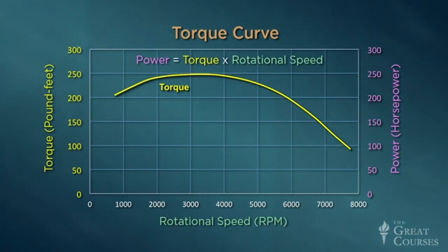On the high end, this deviation from the ideal is the inevitable result of mechanical friction, as well as the air resistance associated with the intake and exhaust flows into and out of the cylinders. On the low end, the loss of torque is caused primarily by convective heat loss through the cylinder walls during the compression stroke. These losses cause reduced pressure in the cylinder and, as the Otto cycle diagram tells us, lower pressure translates into lower torque.